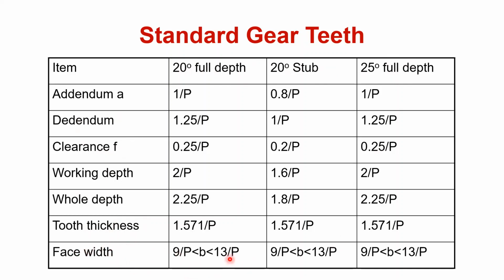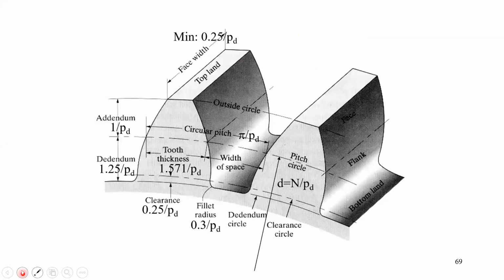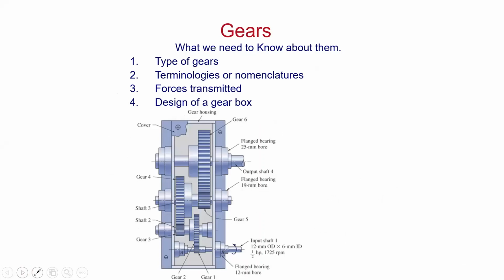But whatever it is, irrespective of the angle, the face width b lies between 9 by p and 13 by p, where p is nothing but the pitch. So again, considering all this, you look at these aspects.